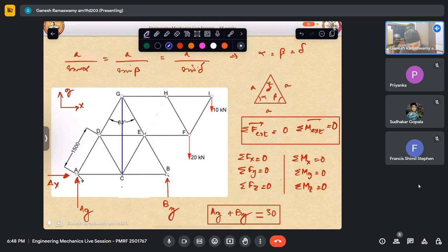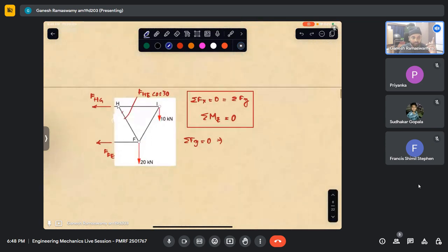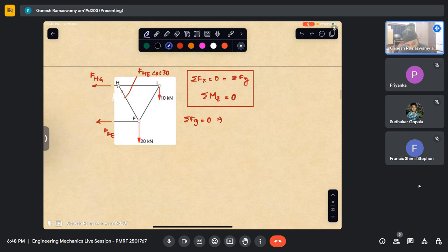Let me put a through member which connects joints E and joint C and G. In this case also this M plus R equal to 2J will get satisfied. But after removing that, if I were to cut the section, this is what I will be seeing as the free body diagram, I hope you agree.